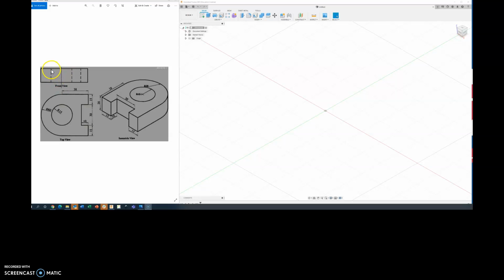So this front view allows you to see that these holes and this gap, these dotted lines, mean they go all the way through. And this solid line represents a center hole. So that's the center of this hole, and it goes all the way through. And here's the bottom edge of that hole, and the top edge of that hole. And then this dotted line is where this little gap is. These dimensions are in millimeters.